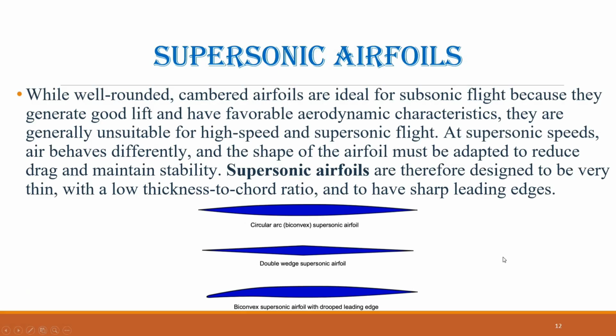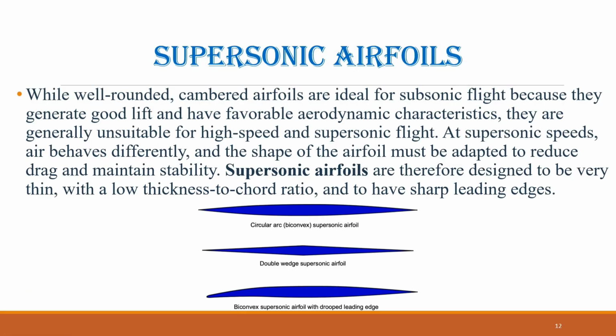Supersonic airfoils. While well-rounded, cambered airfoils are ideal for subsonic flight because they generate good lift and have favorable aerodynamic characteristics. They are generally unsuitable for high-speed and supersonic flight. At supersonic speeds, air behaves differently, and the shape of the airfoil must be adapted to reduce drag and maintain stability. Supersonic airfoils are therefore designed to be very thin, with a low thickness to chord ratio, and to have sharp leading edges.